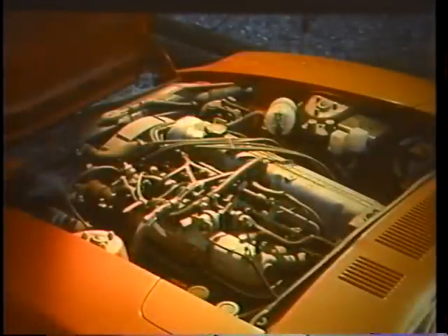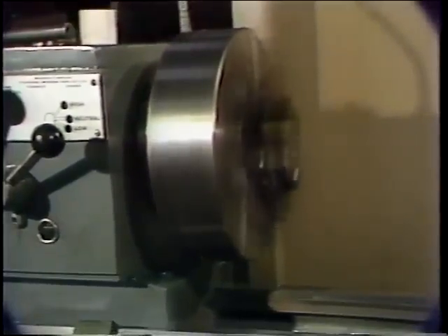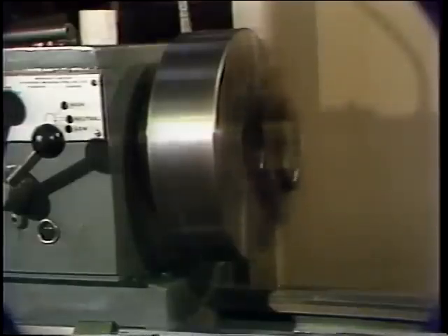An engine oil is likely to be used where the working environment subjects the oil to severe conditions. Severe operating conditions make it necessary to periodically replace the oil. Spindle oil is used to lubricate bearings on small shafts, especially when the shafts are turning at high speeds. These shafts are often called spindles. Spindle oil is highly refined mineral oil with low viscosity. It can be used for lubricating delicate instruments and other sensitive equipment.